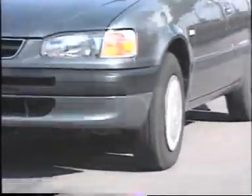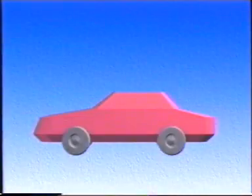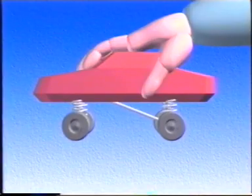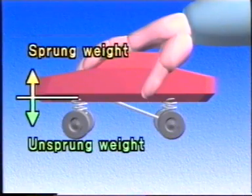The relationship between unsprung and sprung weight also affects riding comfort and steering stability. Let's suppose that you grab the car body and raise it up. The wheels, axles, and brake system hang down. The weight of these components is called the unsprung weight. The weight of the other components, including the body, is called the sprung weight.